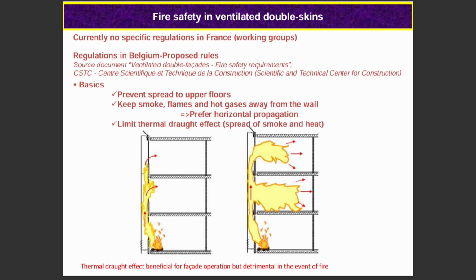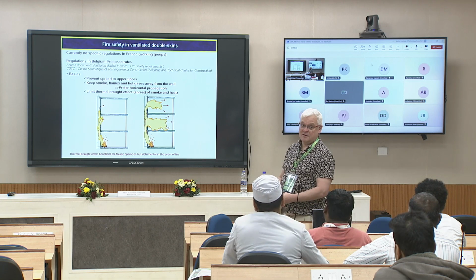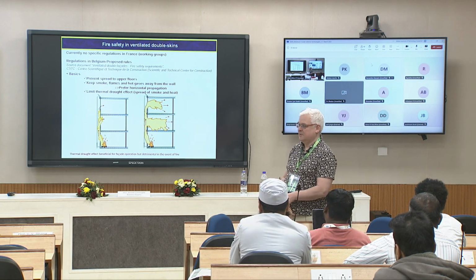For example, for the facade at Technal, the aluminium company, we found solutions in order to avoid, if there is some fire, the development of the fire all along the building. Because if you want to enhance the chimney effect for the sun, if there is a fire, you will enhance the chimney effect for the fire.